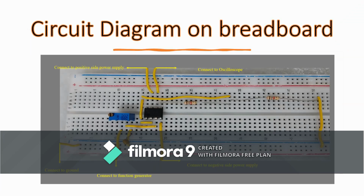So this is the circuit diagram which I built on the breadboard, and from the diagram we can see that the components I use are only one op-amp, which is the UA741 op-amp, one variable resistor, one capacitor, and two resistors. The two resistors represent R2 and R1, and the variable resistor and the capacitor represent the RC circuit. I have also stated clearly how I connect all the wires to the power supply, oscilloscope, or function generator.